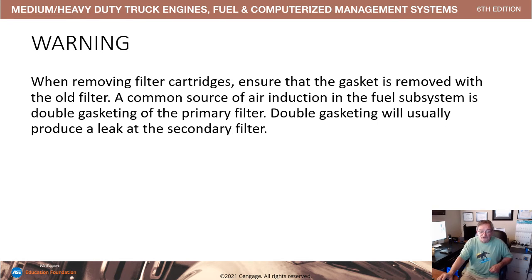Removing filter cartridges, ensure the gasket is removed with the old filter. A common source of air induction, or what's called a vacuum leak or pressure leak, is double gasketing, which will usually result in producing a substantial leak in the secondary filter.